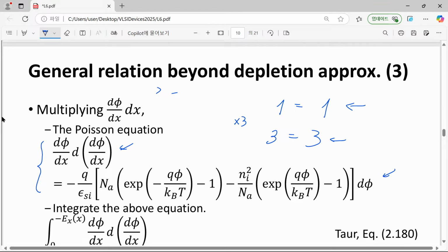Okay, time is up, so I have to stop now. But let me just emphasize once again. Today, we just reviewed our previous lecture. We have to solve a MOS equation. However, the MOS equation has two unknown variables: surface potential, the potential of band bending inside the semiconductor, and the oxide one. However, that oxide one can be just converted into electric field, surface electric field. So now our goal is to find the relation between surface electric field and surface potential.